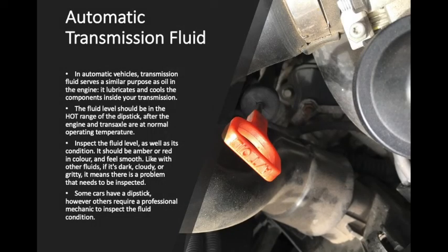In automatic vehicles, transmission fluid serves a similar purpose as oil in the engine. It lubricates and cools the components inside your transmission. The fluid level should be in the hot range of the dipstick after the engine and transaxle are at normal operating temperature. Inspect the fluid level as well as its condition.